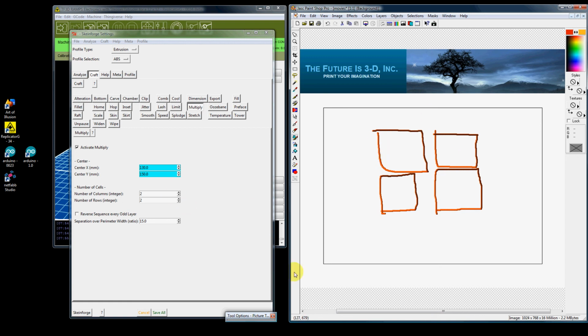And what's nice about the skirt function, if you watch the video on skirt, the skirt will actually start printing. It'll come in, it'll outline the area it's going to print. So if you put, say, 50 by 50, something crazy, your skirt will be out of area, and then you don't waste your time printing something where it's going to fall out of the area. So it kind of tells you where you're going to print, and you can actually watch your skirt as it goes around and make sure your head is just the right height above your bed to make a nice line. It pushes it down just a tiny bit so it adheres to the bed.